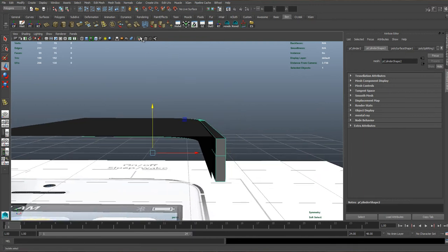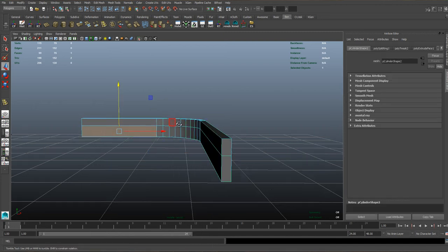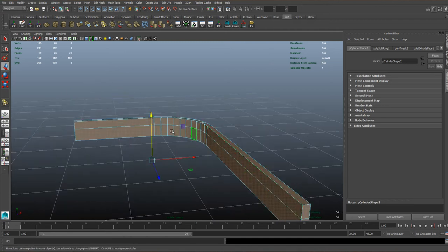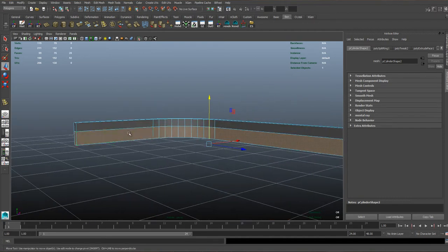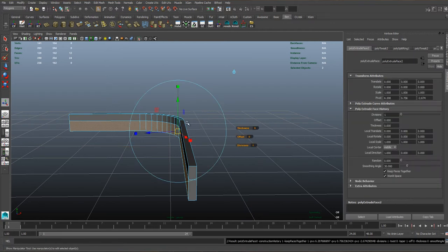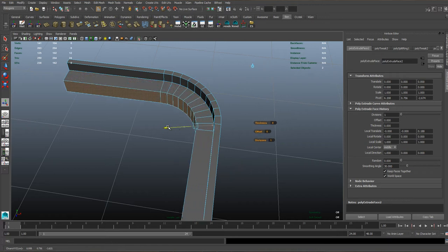So I'm going to click on this icon here, the red cursor with the green selection box, and everything else will disappear. I'm going to select these faces here, so select that face, hold down Shift, double click on the furthest face that you want to select, and it should join up in between, as opposed to doing this where you double select the entire edge of the whole object if you're unlucky. So that face, Shift, this face, and then hit extrude. And we're not going to hit the snap to grid button here, we're going to extrude in like this, and it should give us a nice curved edge on the inside of the phone.